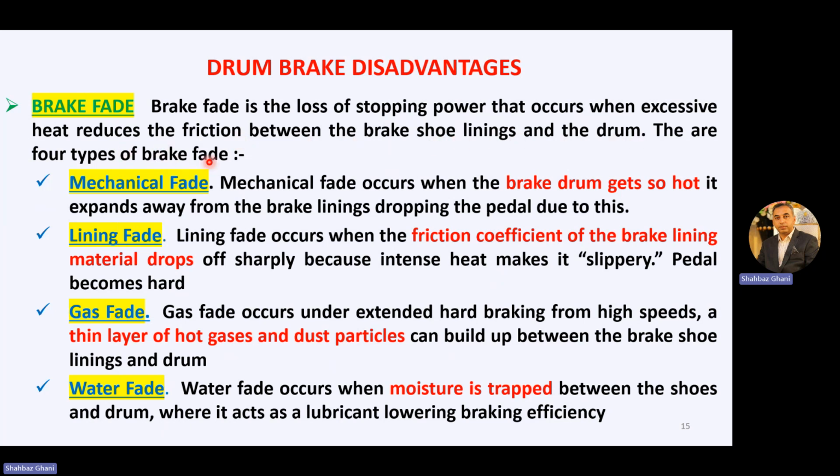There are four types of brake fade. First is the mechanical fade. Mechanical fade occurs when the brake drum gets so hot it expands away from the brake lining, dropping the pedal due to this.